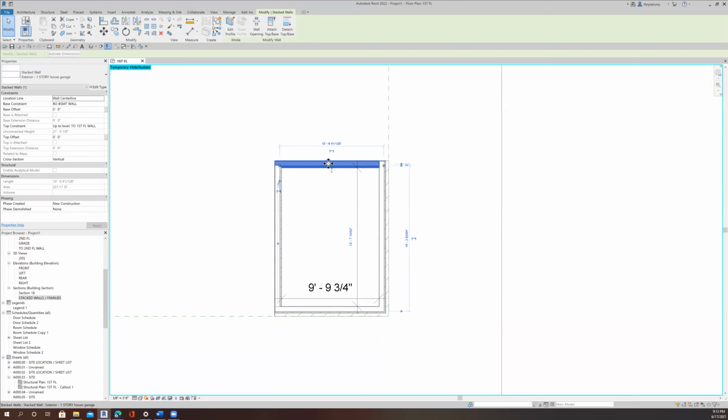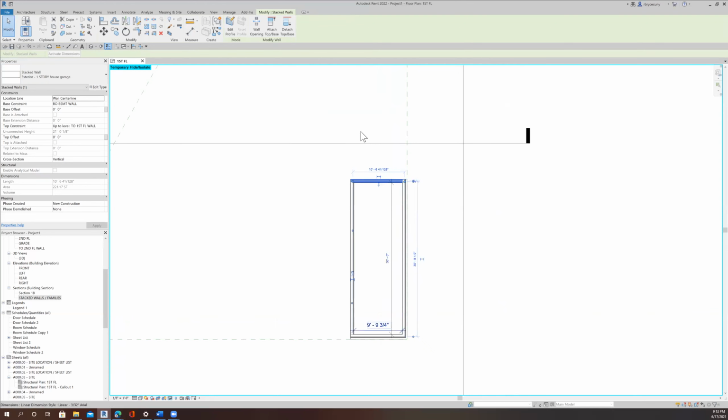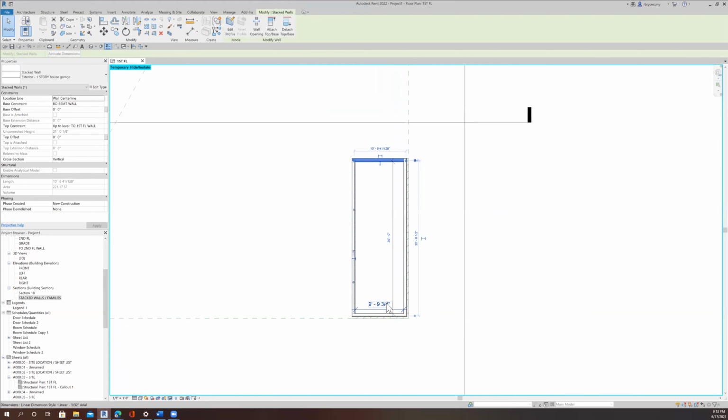Now I'm telling Revit that I want to change this dimension, and I want Revit to change that dimension by moving the object that I have highlighted. So that's why I selected this wall, and then I said activate dimension. And now, just for scale, 30 is probably going to be too small for the garage. It'll probably be larger than that. That's pretty tight, 30 foot for a 3-car garage.